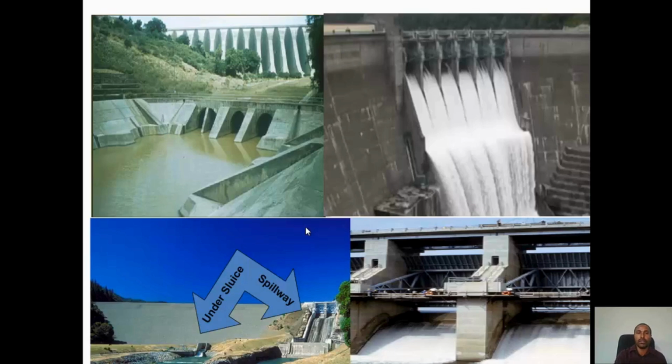So let us see. You can see these are just pictures of dam appurtenant structures. You have dam outlet works here, and this is a buttress dam. For this buttress dam, you have a bottom outlet. This is the bottom outlet, one dam appurtenant structure, and this is a spillway, which is an Ogee spillway with a bucket type at the base at some point here. It will just eject in this direction.